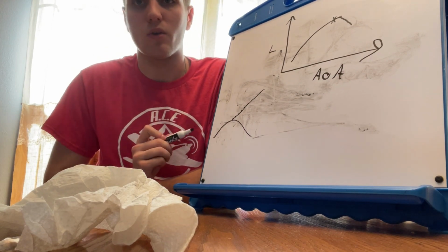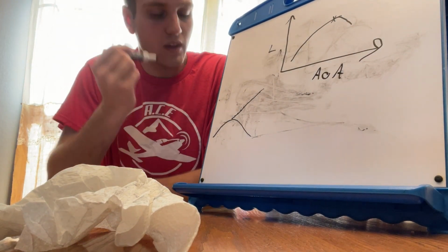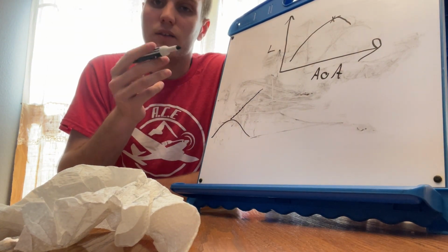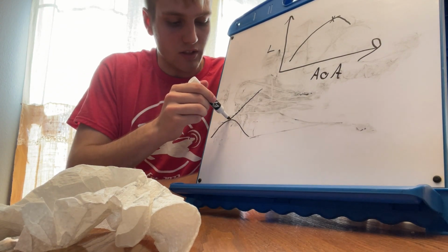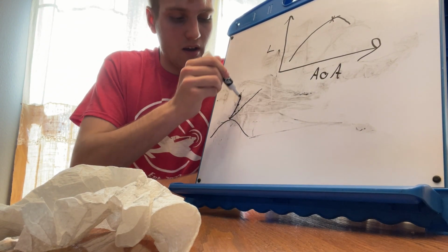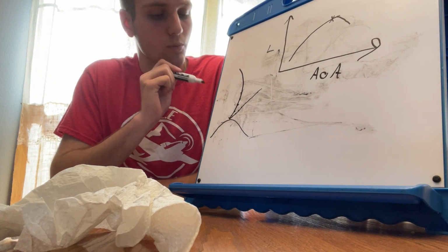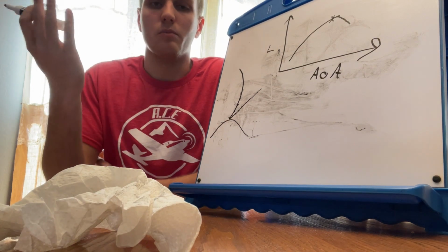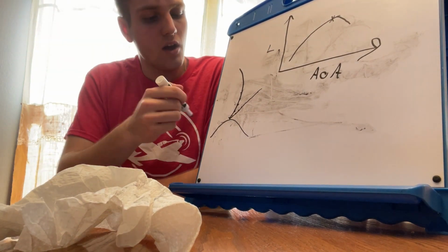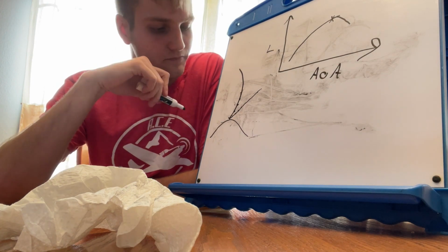It continues on the course that I let go. So that would be neutral static stability. And then you have negative static stability, where I pull back on the yoke, I let go, and it actually increases and does one of those. That would be a very bad airplane. You would not want that type of stability in your airplane because it would be unflyable. So that's static stability, it wanting to return right back to the point.